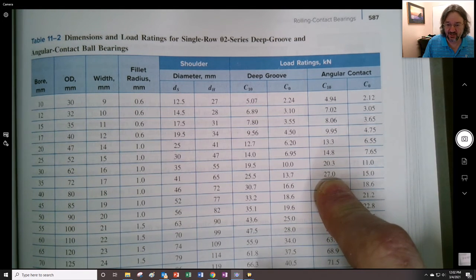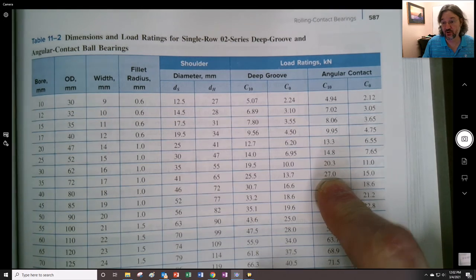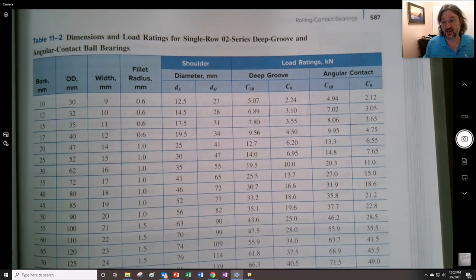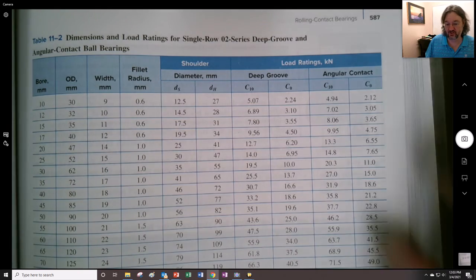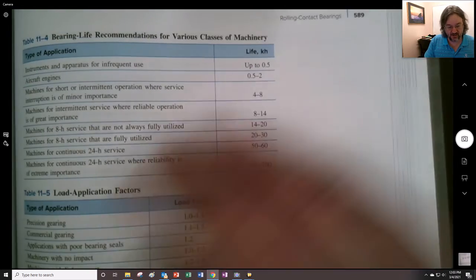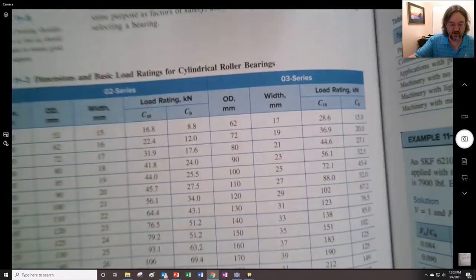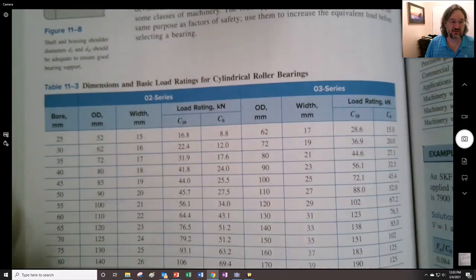So that makes sure our shaft has at least that amount of diameter. We might need to design something with a bigger shaft because the bearings drove it, or we might need to pick another kind of bearing. And of course, we need to use a different exponent.